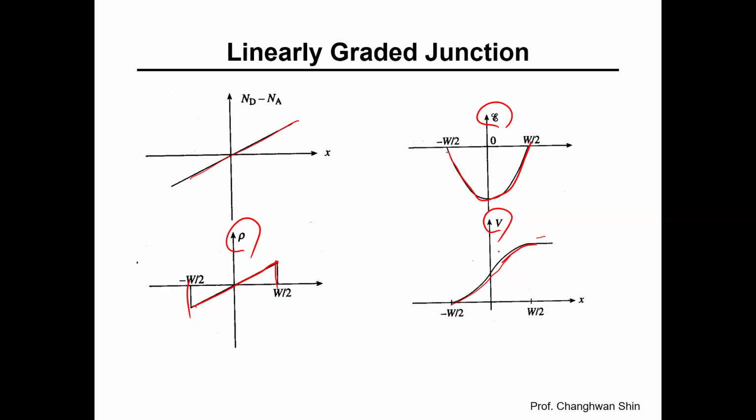This type of junction is often encountered in devices where diffusion processes naturally create gradual doping transitions, or where specific graded profiles are engineered for particular electrical characteristics. The physics and mathematics of graded junctions are more complex than abrupt junctions, but the fundamental principles remain the same. Charge neutrality must be maintained, and Poisson's equation relates charge density to electric field and potential.